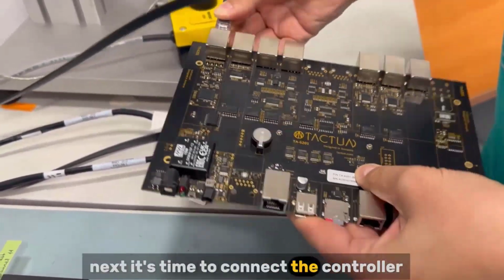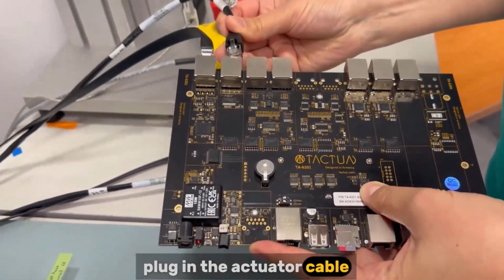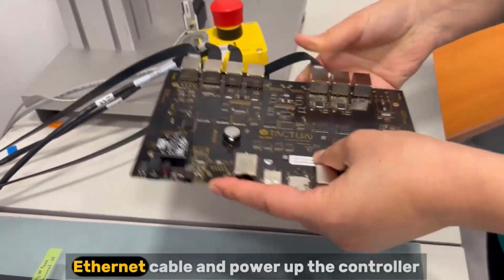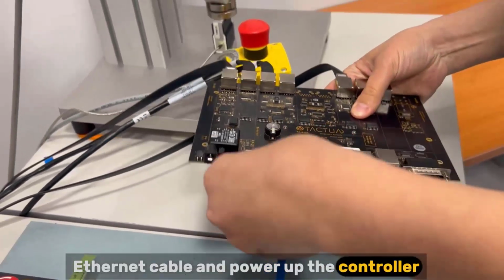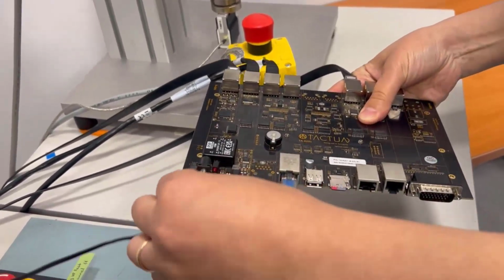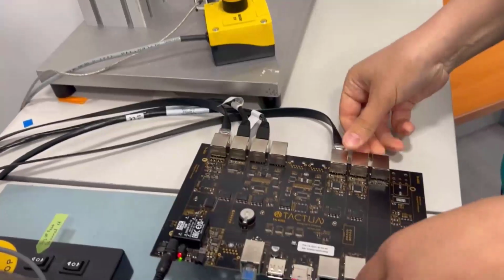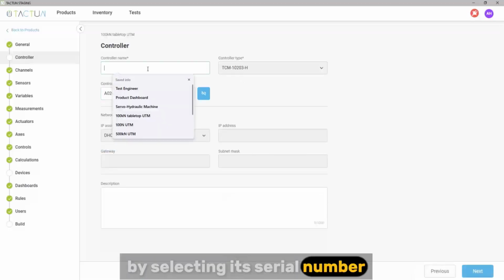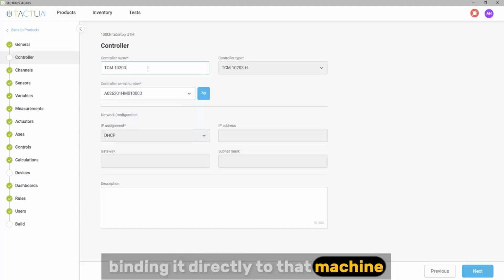Next, it's time to connect the controller: plug in the actuator cable, load and strain channels, LVDT sensor, Ethernet cable, and power up the controller. Connections are complete. Now assign a controller in the software by selecting its serial number, binding it directly to that machine.